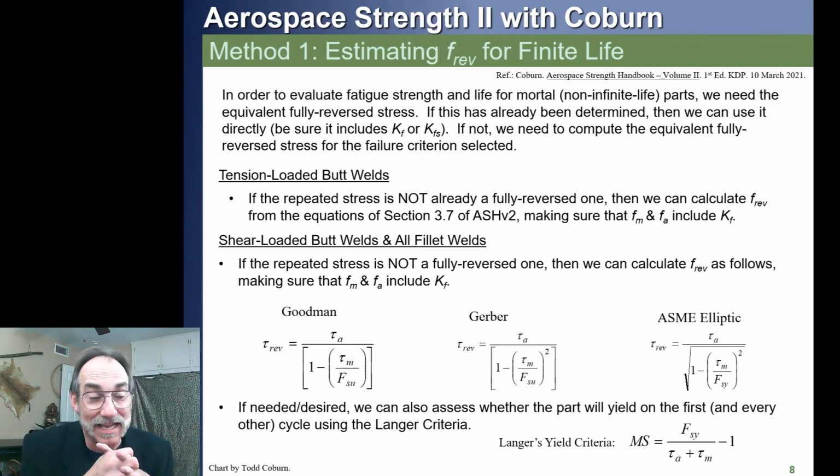Now, even though this doesn't mean that we fail our fatigue check, what it does mean is if you're getting yielding in each and every cycle, it's very possible that your part will not behave as well as you think it is. So unless you develop the testing for this particular material, it's very possible that you're going to estimate something's good that may not be good. So you may need to look a little more closely.